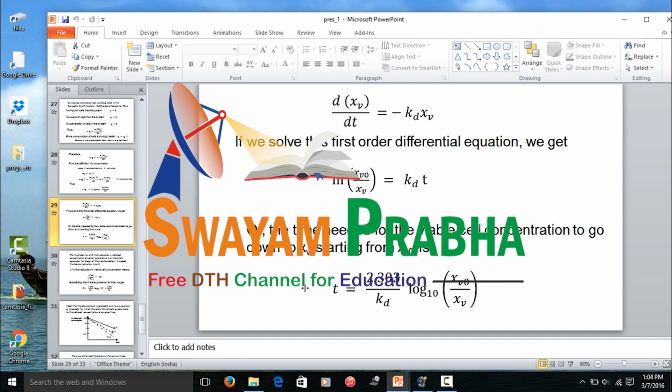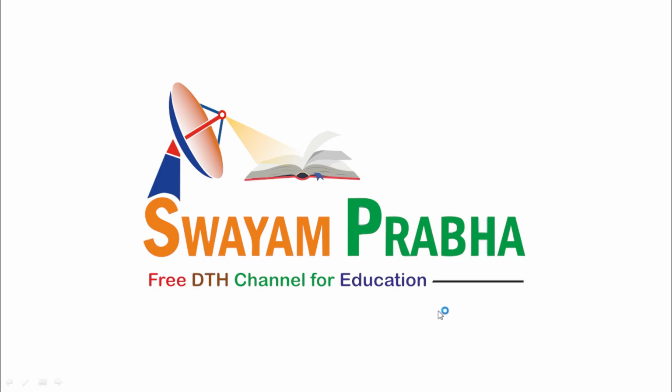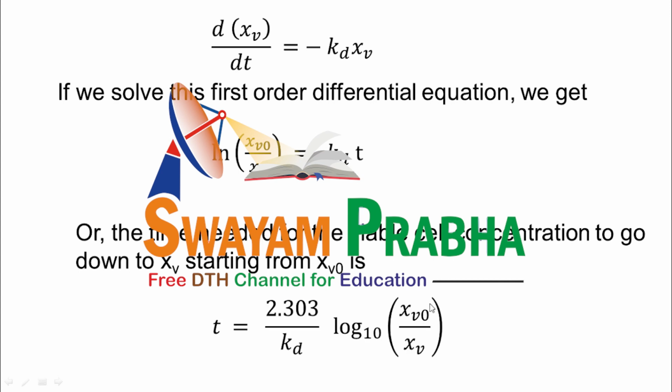This was the time that it takes for the cell concentration, the time taken for the cell concentration to go from a viable cell concentration initially xv naught to a final viable cell concentration xv: 2.303 by kd, this is a constant, times log to the base 10 of xv naught by xv.